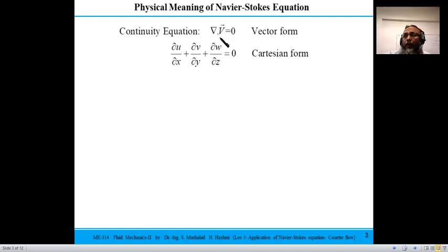So far what we have learned is that it is depicting the fact that for fluid coming into a certain region of interest, the rate of change of mass would depend on how much is coming in and how much is leaving. So if there is no source term, or no mass is being created in the region of interest, the divergence of velocity would be 0.